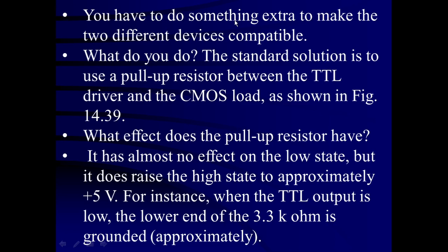Because of this, you cannot get reliable operation by connecting a TTL output directly to the CMOS input. You have to do something extra to make the two different devices compatible. So directly it cannot work. Something has to be done so that the two devices can be compatible to each other. What do you do? The standard solution is to use a pull-up resistance between the TTL driver and CMOS load, as shown in figure 14.39.